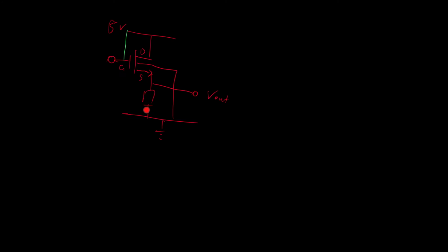In our second attempt, it's the same as before, but we're connecting the substrate to ground in the hope that if we connect the gate to 5 volts, then because we have 5 volts between gate to substrate, this FET should be wide open. But remember what we said, there's also effectively a diode between the source and the substrate.